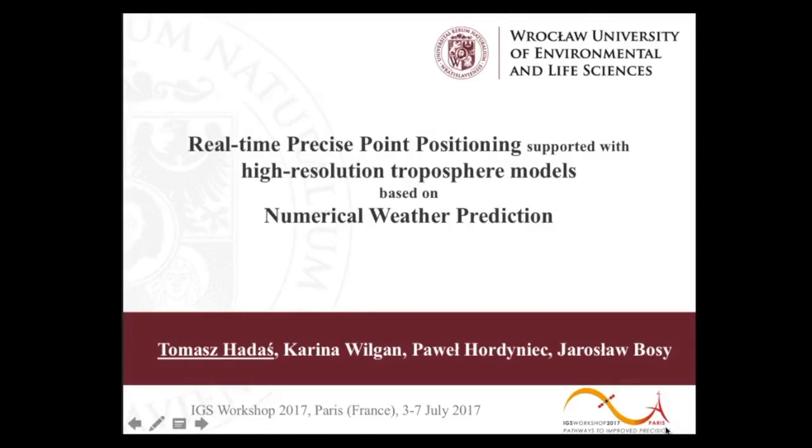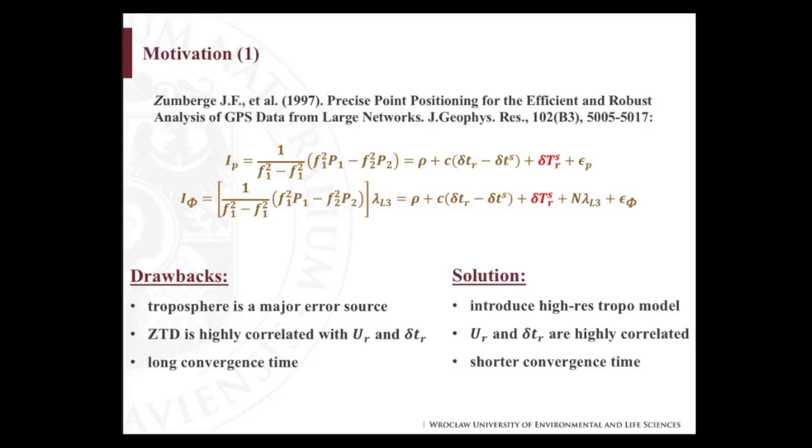So, as you probably know very well, the consequence of using the ionosphere-free linear combination in the classical PPP model is that the ambiguities are no longer integer values, and ambiguity resolution is still a challenging task in real-time applications.